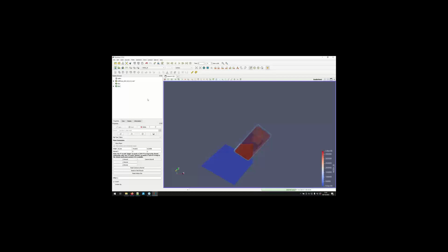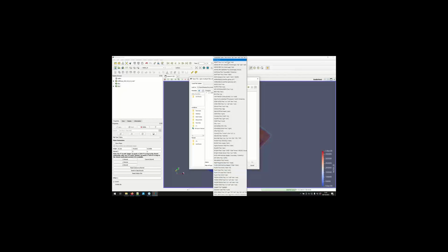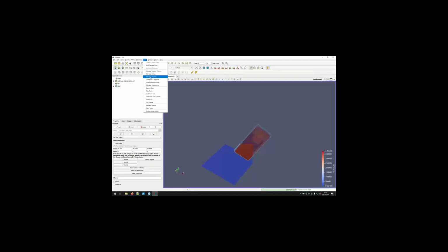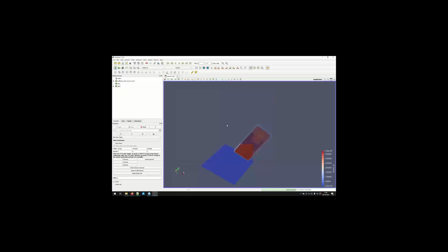If your question is more about the file format, ParaView can open lots of file formats. If you click open, there is a lot supported, maybe 55 formats by default. And ParaView has a plugin mechanism where you can add new file formats and new features, depending on what you are loading. Med, for instance, is the file format used by Salome and EDF. Slack is also a file format, and so on. I hope I get your question.